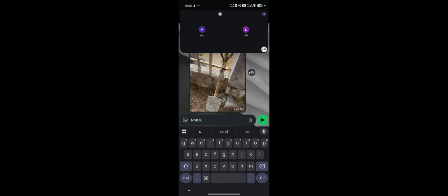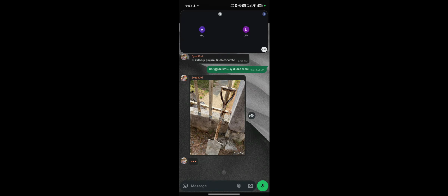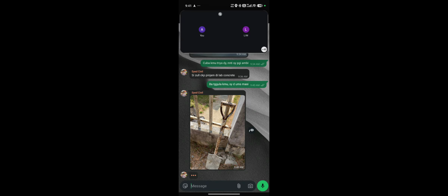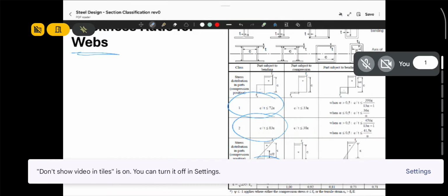But that's for flange. For webs, you go to the next table, next page. So for webs, class 1 is 72 epsilon. Class 2 is 83 epsilon. Class 3 is 124 epsilon. Okay. Clear, so Doctor, that's where I got the 72 from. Yeah. Thank you.